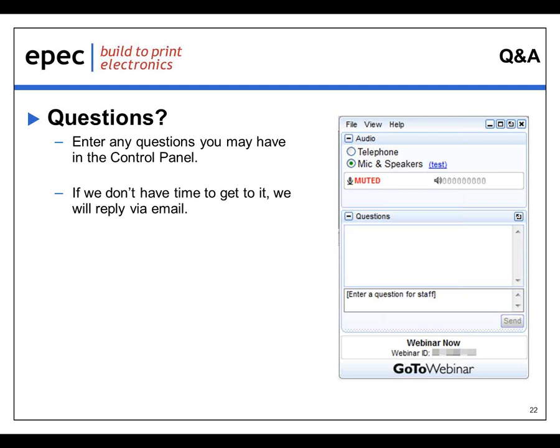Can you elaborate on how you go about executing layer count reductions as a means of cost reduction? It's a great question, actually, and it's something that we do quite frequently. We work with customers to take layers out of existing designs, not necessarily changing the components per se, but literally redesigning the architecture of the board so that we can drive layer counts out. And they're really driven by a variety of situations.